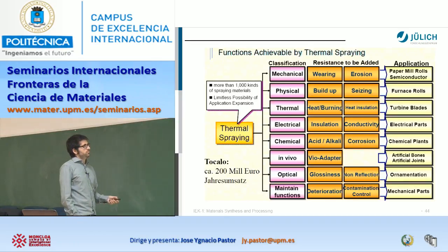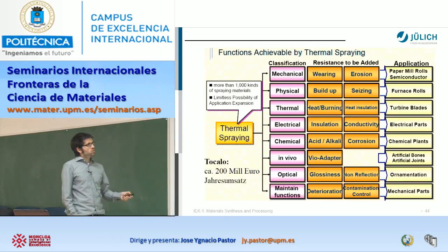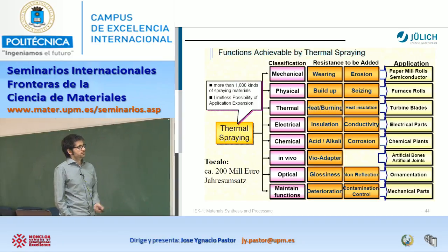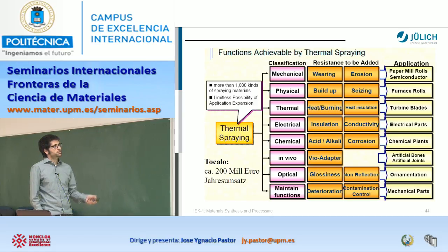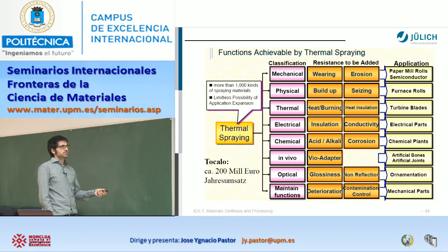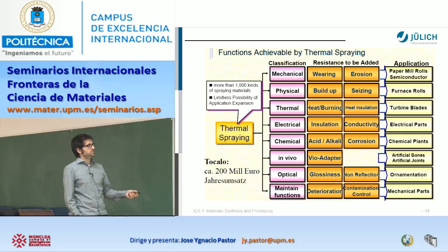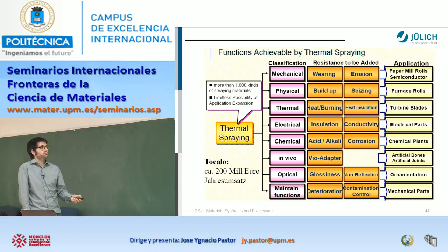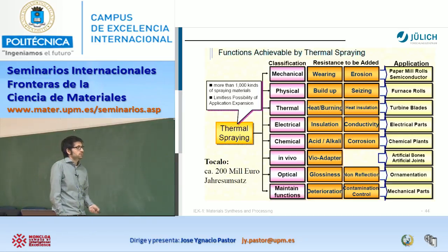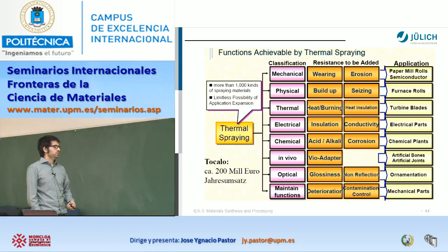Well, more examples about in what field can work or not, in function of the technique for the thermal spray, but as you see, there are several different possibilities. Of course, we are talking about the outside layer, and then we can modify the mechanical, the physical, the thermal properties, of course, with the TBCs, also electrical if you want to insulate something, or on the other hand, you need to do conductive parts, chemical also for bio things, optical, I mean, practically everything.